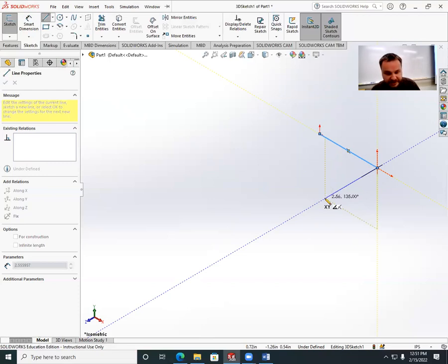When you're drawing lines, if you hit the Tab key, and your tutorial is going to walk you through this, it will change the direction that you can draw those lines. You can only draw lines in 2 directions. And so now I want to draw 2 inches in the Z direction.